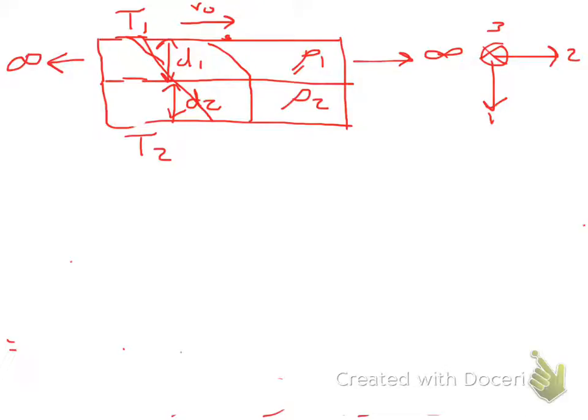In this one, we're keeping the temperature steady, but if we wanted to transfer more heat, if we wanted to transfer heat out faster, given the same temperature at the boundary, what would we change? How do you increase the heat flux? What's the equation for heat flux? You could increase the conductivity or increase the gradient, right? dT/dx, times the conductivity gives us the heat flux.